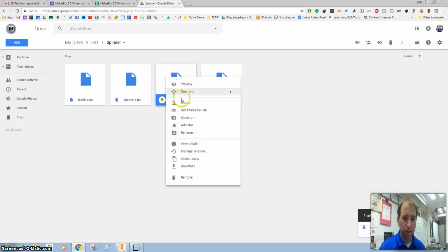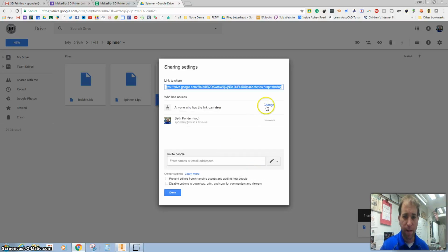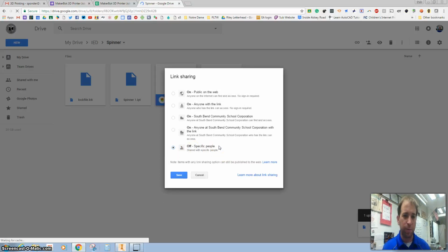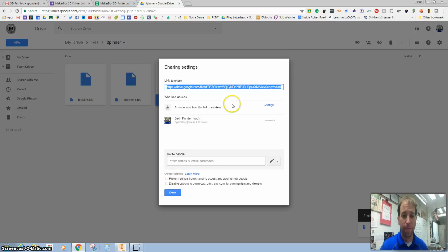Right-click on here and go to Share. So I'm right-clicking on my STL file, going to Share. I'm going to hit Advanced and Change. So this is pretty cool because it sets it here to off. Only specific people like myself can see it. But I think it's pretty cool when people want to share out to the online community what they've made. So I like to do anyone with this link. Now, they can't edit my project. They can only download it, and if they have a 3D printer at home or at their library, they can use it there. So I'm going to hit Save.